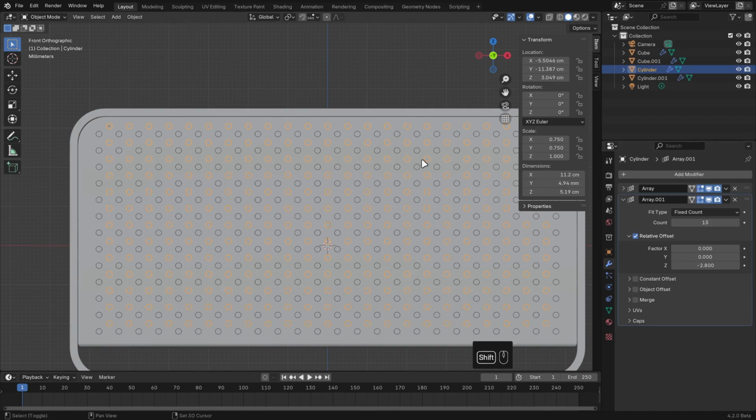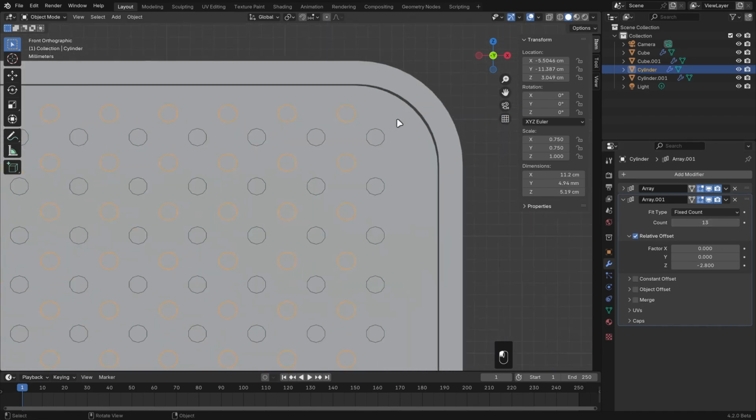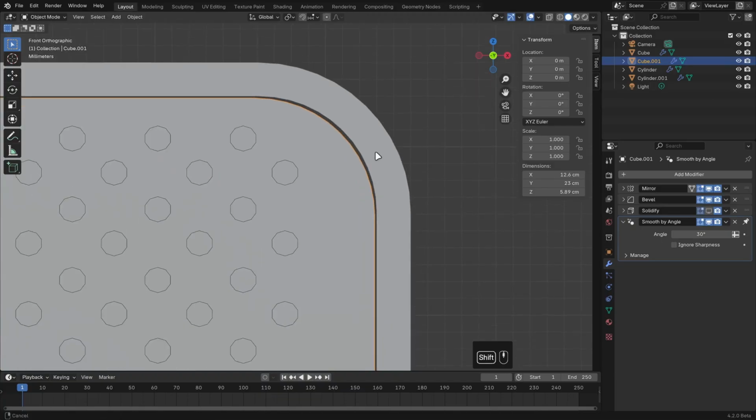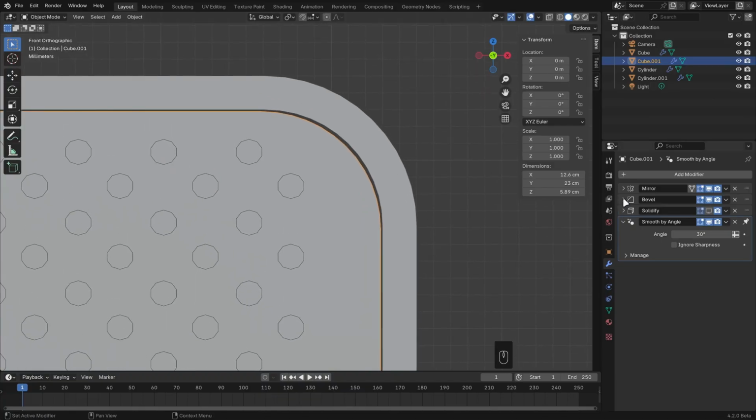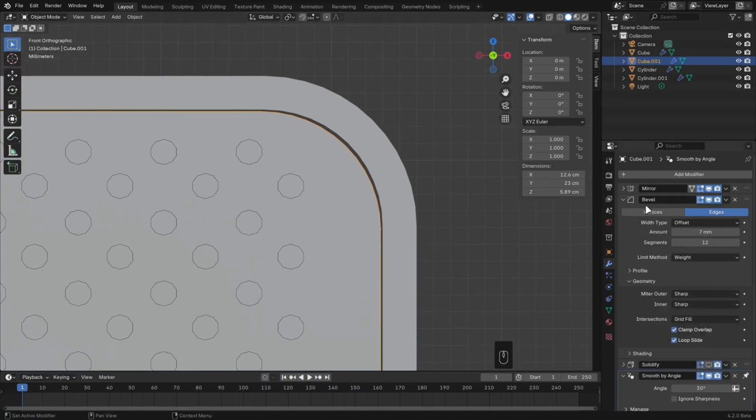Before we go any further, it is bothering me a little bit that this bevel isn't quite exact. There's a little bit too much space there, and maybe I'm being a little bit too picky, but we can go ahead and fix that by going over to the bevel modifier, holding down Shift so we're working in really small increments, and try to get that as close as possible, though it doesn't look like it's going to let us do it. So let's go